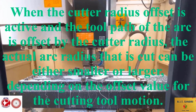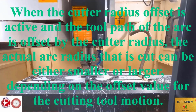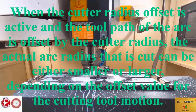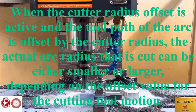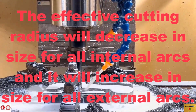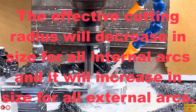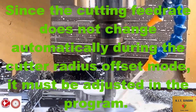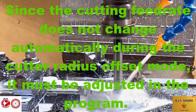When the cutter radius offset is acting and the tool path of the arc is offset by the cutter radius, the actual arc radius that is cut can be either smaller or larger depending on the offset value for the cutting tool motion. It is important to understand that the effective cutting radius will decrease in size for all internal arcs and increase in size for all external arcs, since the cutting feed rate does not change automatically during the cutter radius offset mode. It must be adjusted in the program.